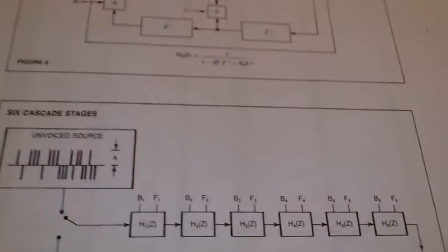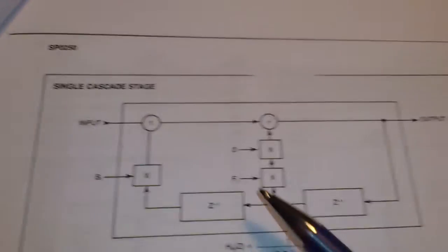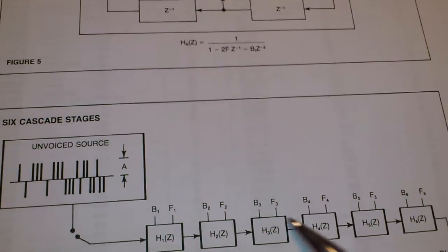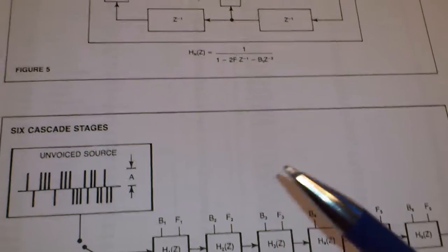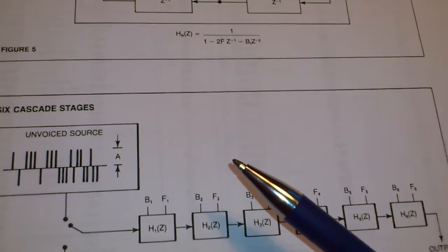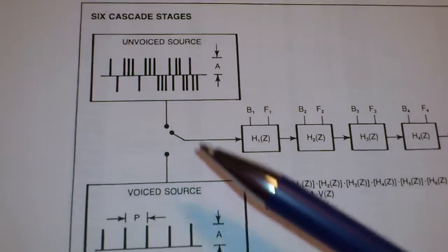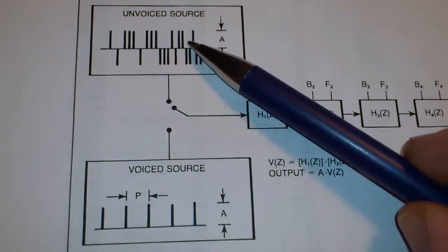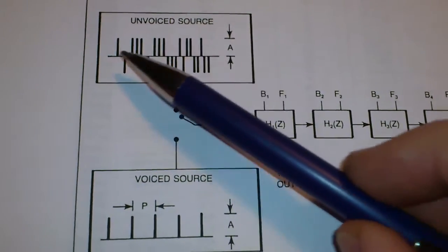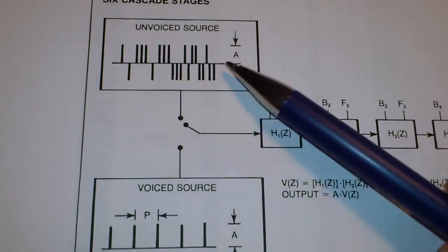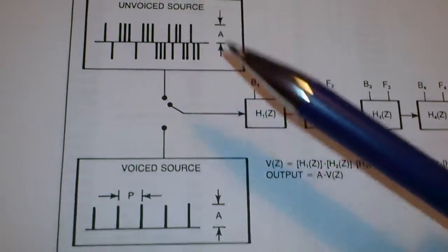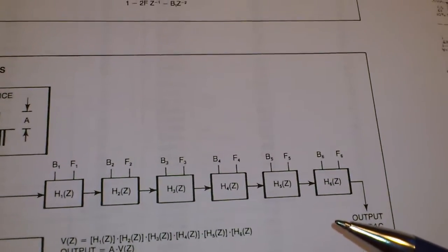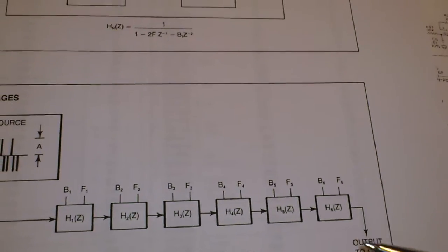So I've been doing this in the FPGA, so I have been doing this filter stage once. I have been just replicating it 6 times. I load this over the interface, there are parameters in. I change the parameters by the ROM, so the filter quantization table. I generate 2 different ones, where really this one is the important one. This one I've tried a little, but it doesn't sound really good because you don't really know what kind of feedback polynomial is here to get the randomness. Yeah, in the end I put a low pass filter to get the high frequency noise components out of the signal.